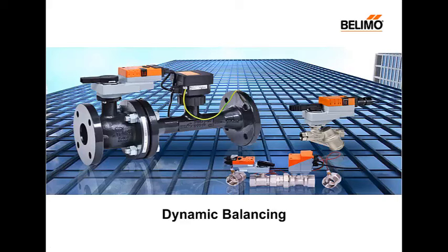Today's topic will be dynamic balancing. Normally on our webinars we do more product-focused subject matters, but today we will be discussing a key point in the hydronic balancing of your building. And what we'll talk about is how pressure-dependent valves leave your building statically balanced, while dynamic balancing comes only from using pressure-independent style valves.